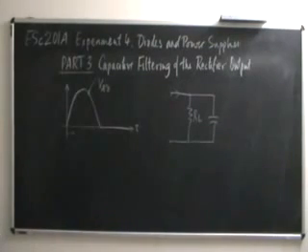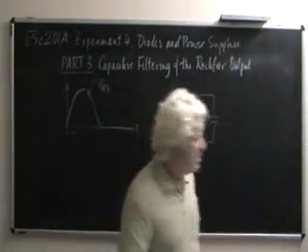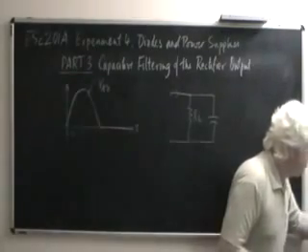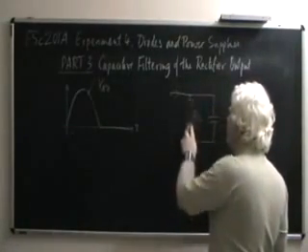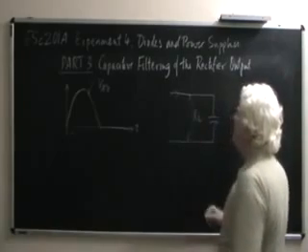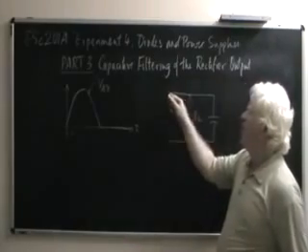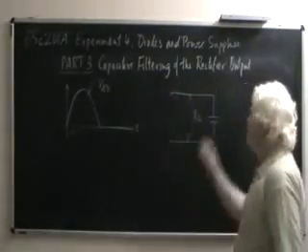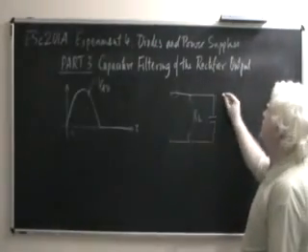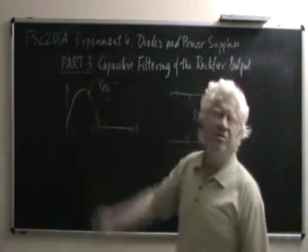After this point, let's pretend for a moment that the load resistance is absent, and let's assume that the diode is ideal. So the diode in the rectifier behind this is also ideal. This capacitor has now been charged to what we can call Vm, the peak voltage of the sinusoid.